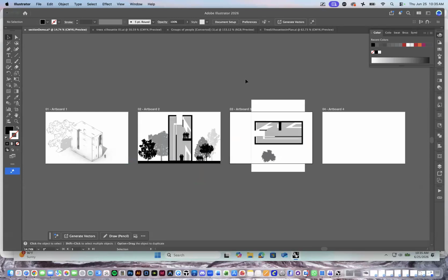If you are still working on modeling things, take a break from that, pause, and go through this workflow. Make the clipping plane, cut the section, cut two sections, bring them out, bring them into Illustrator. Try this workflow sooner rather than later.